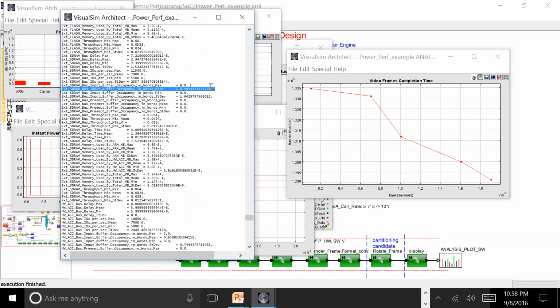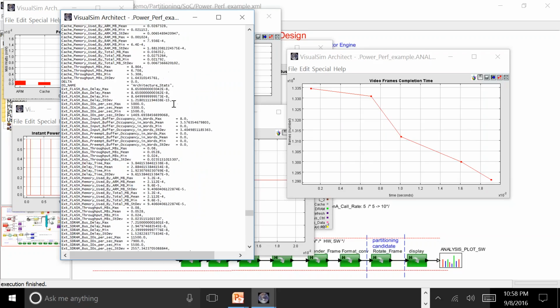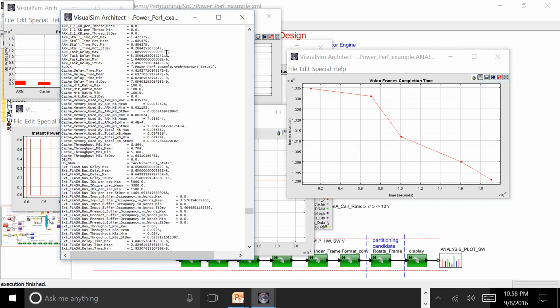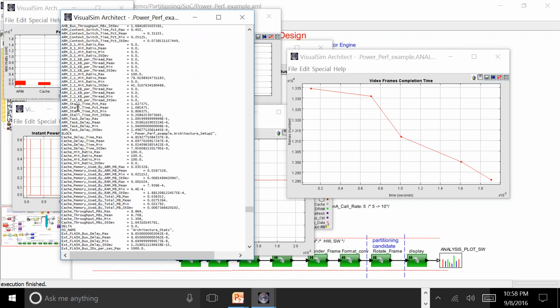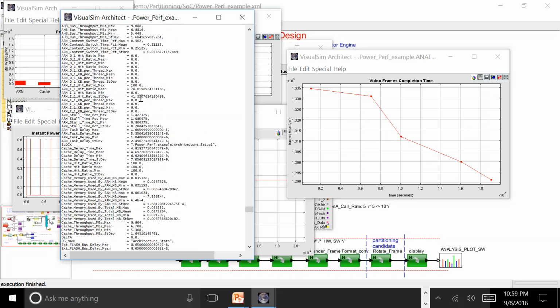So one of the things you're going to notice is I've got a significant amount at peak time. I've got about 8 words that are being backed up on the DRAM, which means they're being buffered on the DRAM. This tells me that potentially the memory controller buffer could be extending, so you might have a higher amount of queuing delays. Now, if you go back and look at the cache and get a feel for what is the stall time, you can see I'm already getting about a 1% stall. Not significant, but I'm getting a stall of 1%.